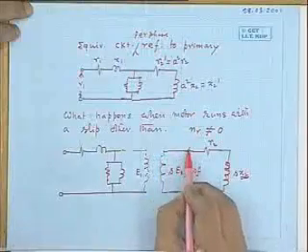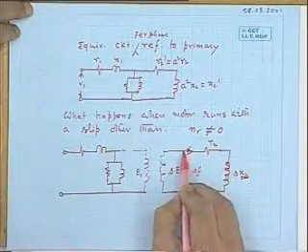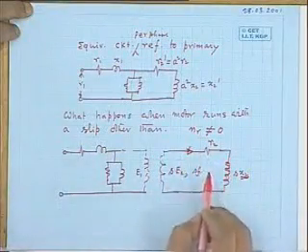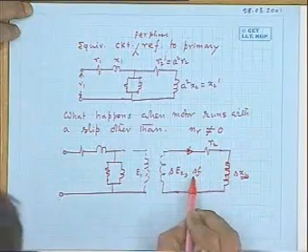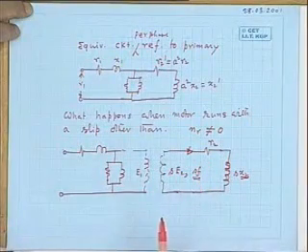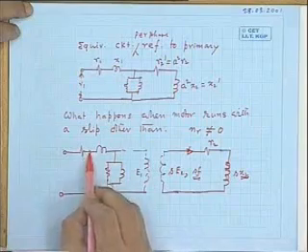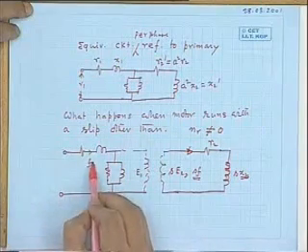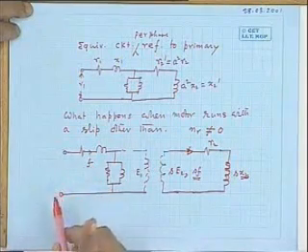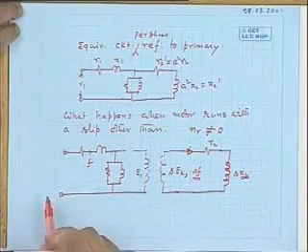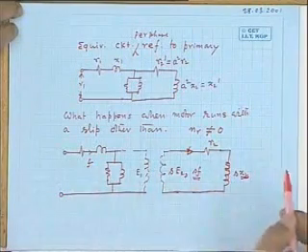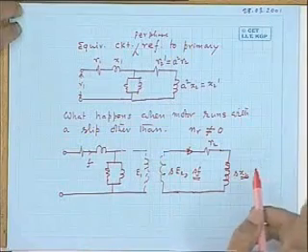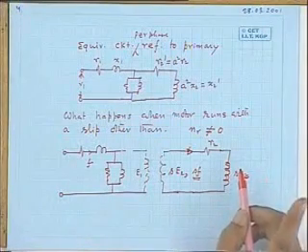Now the question comes, here of course some current will flow in the rotor circuit, but the frequency of this current is SF, and the frequency of the stator current will always remain F, because as I told you, the stator will react when there will be a rotor current.